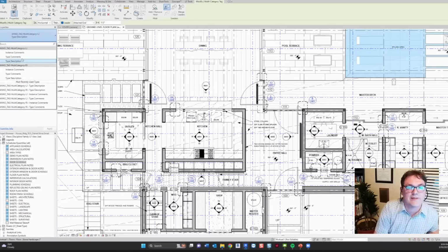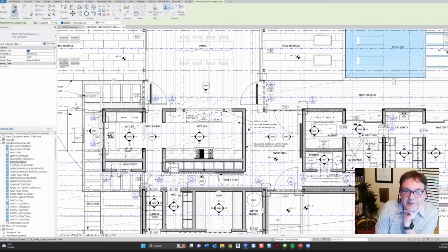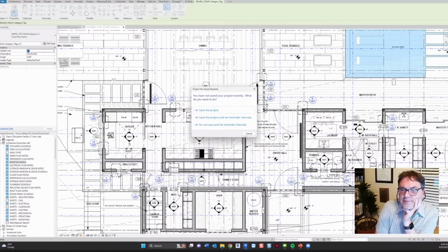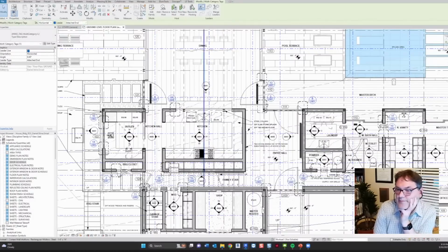The type comment is something that we can have in the component, and then if there's some variation on that instance, we can edit the instance comment, which gets concatenated with the tag that's labeled. Yep. So it might be steel, and then the instance parameter is painted or primed or something. So PP1. So it's not keynoting, but it's smart tagging, kind of, is the approach there.